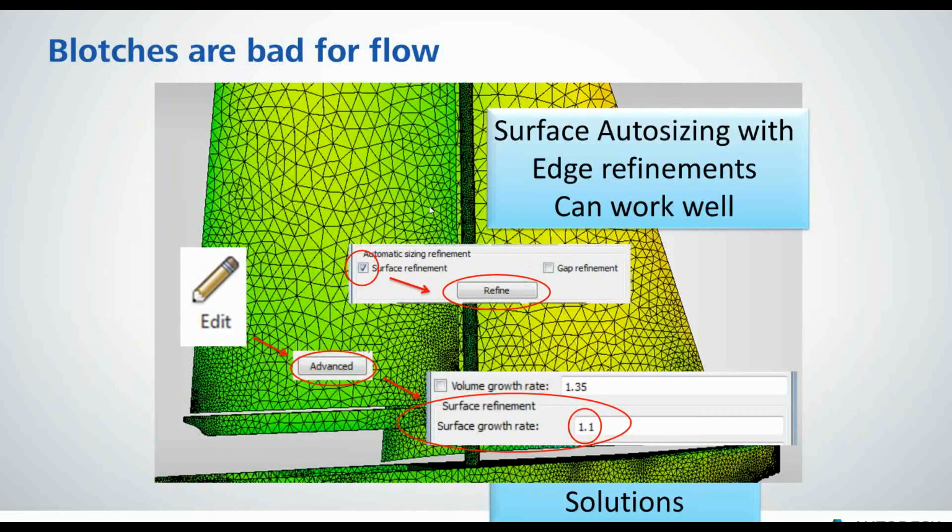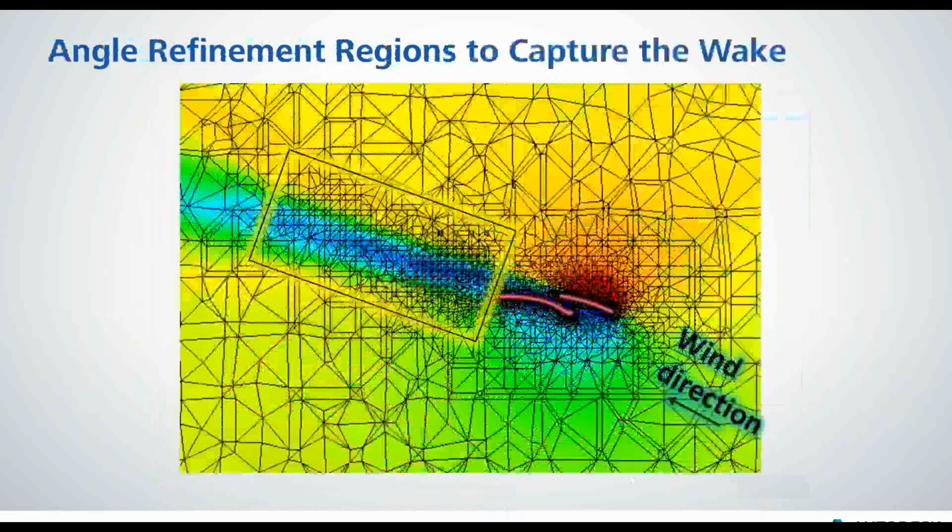Last, one of the things peculiar about meshing for external flow volumes is we've got to treat that wake. I just told you about how important that wake is. So we have mesh refinement regions. Whenever you need more mesh in a specific area of your model, for whatever kind of analysis, particularly when there's no geometry to help guide the mesh, you can always use these mesh refinement regions to try and capture a wake or a jetting fluid or an area where there's a lot of circulation, perhaps, in your flow.